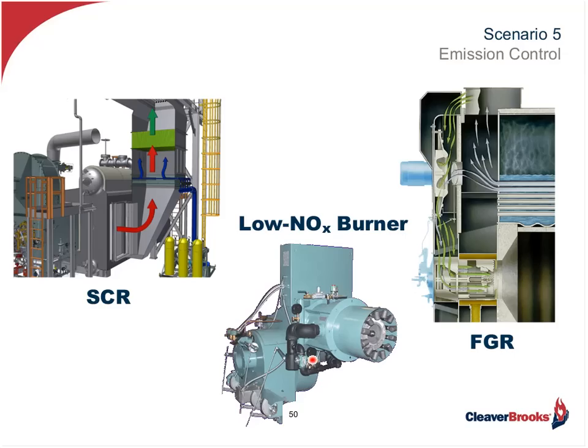But beyond that, and now the regulations are calling for more and more reduction in NOx, we may have to go to flue gas recirculation in conjunction with the low NOx burner to take us down to levels that could be sub 9 parts per million. Remember now, 120 to sub 9. Now when we start getting below that, let's say 4 or 5 parts per million, or even less than that, we may have to go with selective catalytic reduction systems in conjunction with FGR.